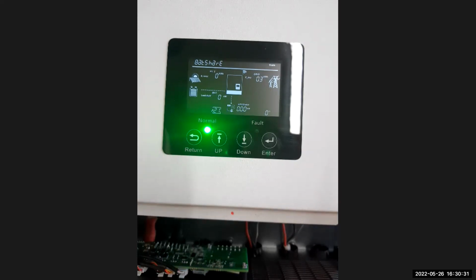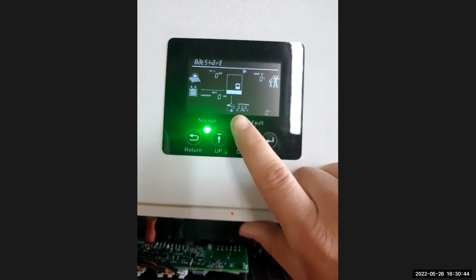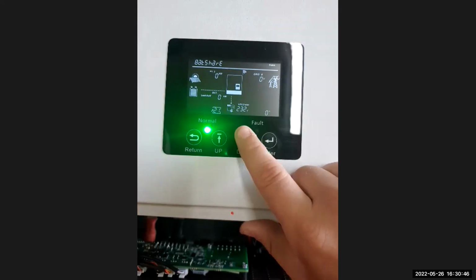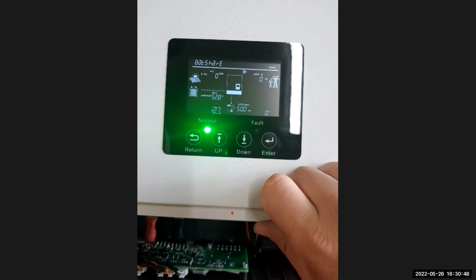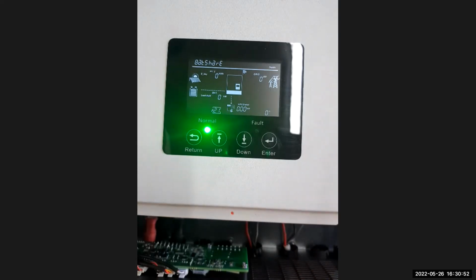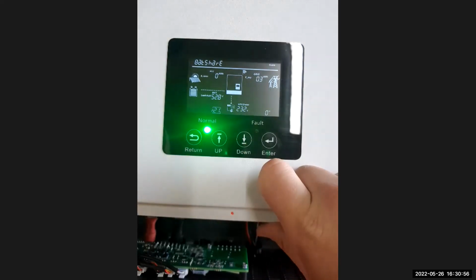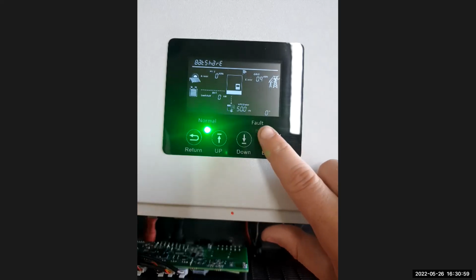So on a battery shared system, you enable it, then the master will relay all the information. And then as soon as you have 2 batteries, where one inverter has its own battery and the other one has its own battery, then you go to your disable option. As you see, it's then disabled. Then each inverter knows the information that it receives from the battery is its own battery. But as I have a battery that's shared between my 2 units, I'm going to press enter.